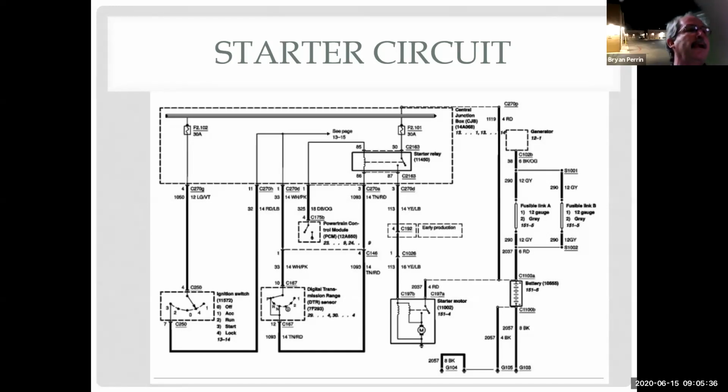So, how many of you knew it took so much to start a car? I knew about the starter, but that's it. Yeah, a lot of people are familiar with either a clutch safety switch or a park neutral switch. They've all experienced not being able to start your car because you don't have it in park or something. I think a lot of people don't necessarily think about that, but when they're asked, they really do know that. But this is a pretty typical starting system.